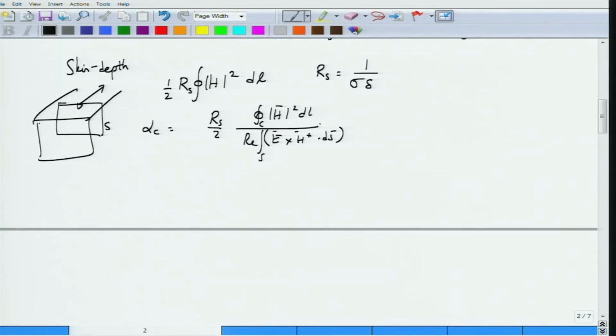So, if you forget that messy algebra and note down the results, you can derive alpha c. Or rather, you can first derive the transmitted power, the denominator part, as 2P10 for the TE10 mode. This 2P10 is equal to AB by 2 omega mu beta |H0| squared. This was in fact E max squared that we had calculated, times (A by pi) whole squared. This is the power that has been calculated for the TE10 case. This was AB by 4, but we need a 2P10 because there is a 2 here.